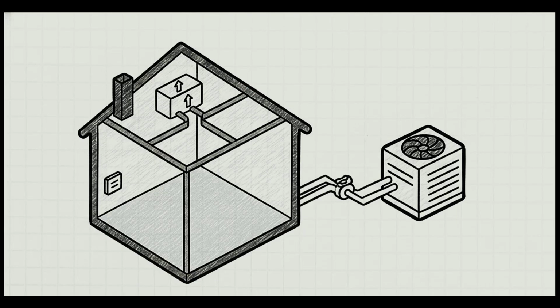Section 2. Anatomy of your AC. To see how this heat subtraction actually happens, we need a mental map of the system's mechanical weapons against the summer heat. Picture a high-quality 3D engineering animation of your home's system. It consists of a few absolutely crucial components working in perfect harmony. Inside, you've got the thermostat acting as the brain, the air handler, the evaporator coil, and your supply and return ducts guiding the airflow. Outside are the heavy lifters, the compressor and the condenser coil, complete with its cooling fan. And bridging them together is the expansion valve.